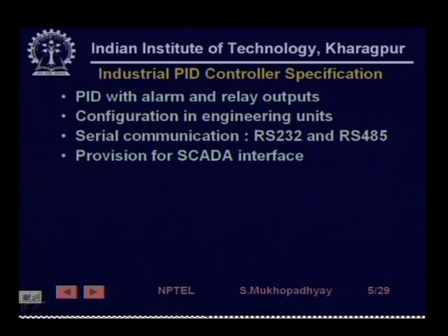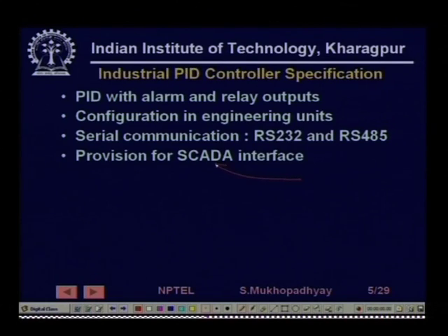Most PID controllers will support communication using standard communication protocols like RS-232 and RS-485. These are used for a variety of purposes. For example, provision for SCADA interface. SCADA stands for supervisory control and data acquisition.